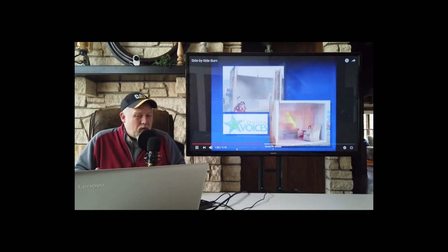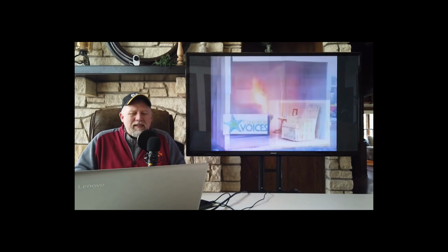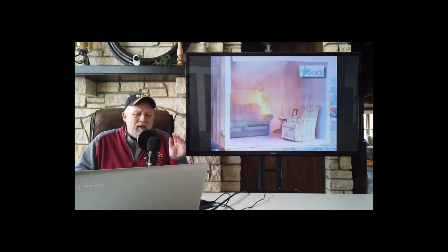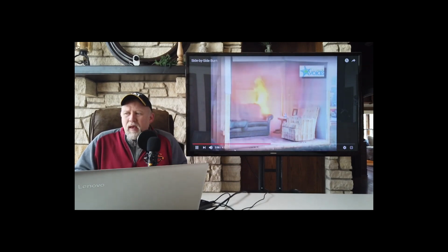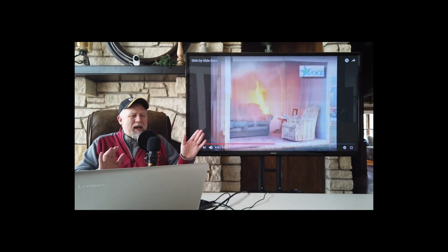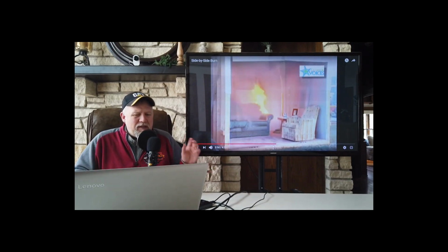Yes, now it's true, everything gets soaked. And it's also true that it didn't eliminate fire and smoke. There's still a lot of damage in living room number one. But it's going to be considerably less compared to what happens in living room number two. So in living room number one, about 2 minutes pass, the sprinkler head actuates, suppresses the fire, gets everything wet, and yes, it'll still smell.